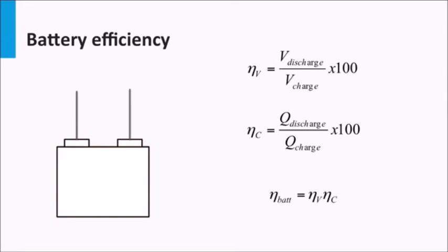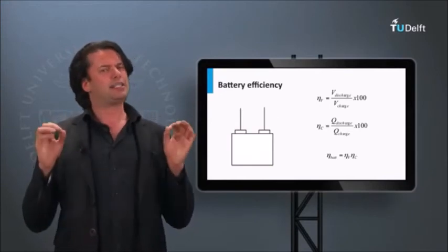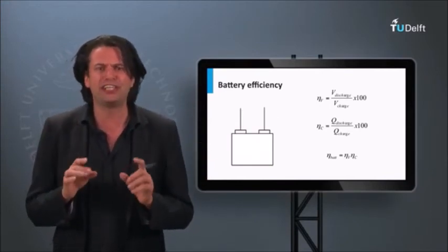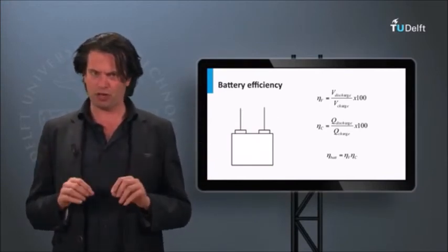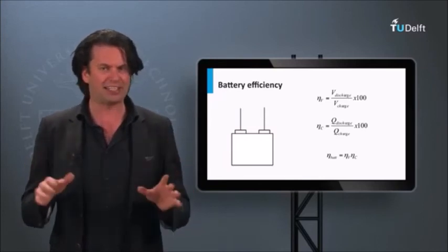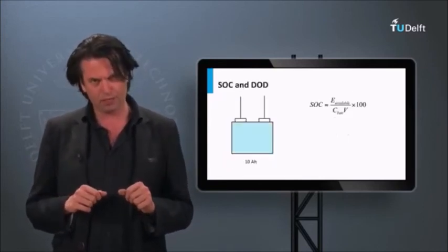Battery efficiency is defined as the product of these two efficiencies. This overall battery efficiency can be seen as the round-trip storage efficiency that is usually considered while comparing different storage devices. This battery efficiency includes the effects of all the chemical and electrical non-idealities occurring in the battery.